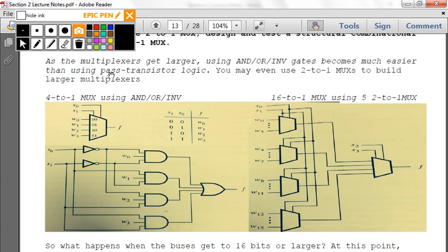You have a bunch of 2-to-1 muxes to pick. Let's call these A and B. So you have A as STD_LOGIC_VECTOR 31 down to 0, and B 31 down to 0, right? Then you can map 2-to-1 mux 31, 31, 30, 30, 29, 29. And then you have how many?